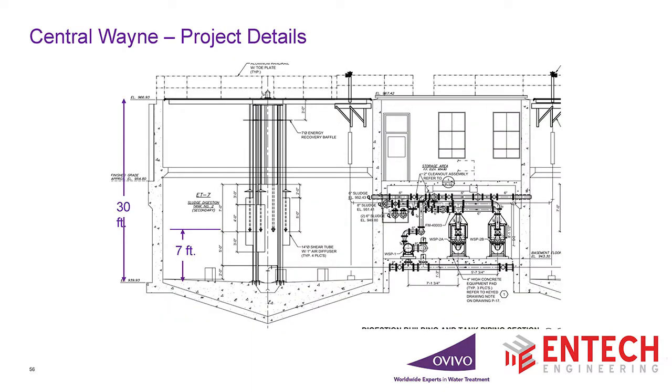And a cross section of this tank, this was a 30-foot deep tank with the draft tube in the center, cover on top. The bottom of the diffuser is 7 feet off the bottom of the tank. That goes to some of your energy savings. We're not pushing air against 30 feet of water. We're pushing it against 23 feet of water. That back pressure is a significant savings. But again, the bottom of that draft tube is 2 feet off the bottom. It's still pulling the sludge from the bottom, giving you this large velocity in the center, carrying your air, transferring your oxygen, and creating a mixing pattern. Next one, Brian.